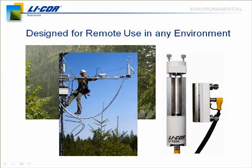As I was mentioning just a moment ago, the instrument was really designed for easy cleanability in the field, and the image here shows you an LI-7200 with the optics opened up for cleaning. Dave talked about this a little bit earlier, but all you do is unscrew the 2 screws at the top of the instrument and pull the top open. Then you can remove the optical cell, and that's the piece on the right there.